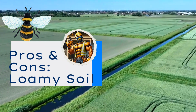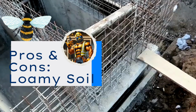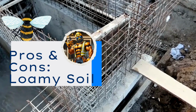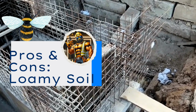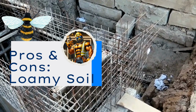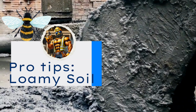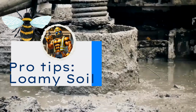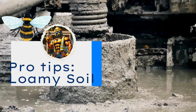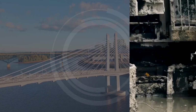The pros of loamy soil are obvious. It's versatile, stable, and offers the right balance of properties needed for a solid foundation. The cons are minimal, but in areas with heavy rainfall, you might need additional drainage just to ensure the soil doesn't retain too much moisture. If you're lucky enough to build on loamy soil, make sure you take advantage of its natural properties by using shallow foundations like spread footings or strip footings. Just ensure that the site is graded properly to avoid excess water pooling around the foundation.